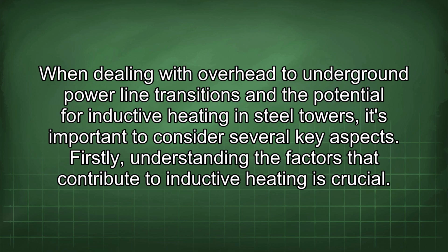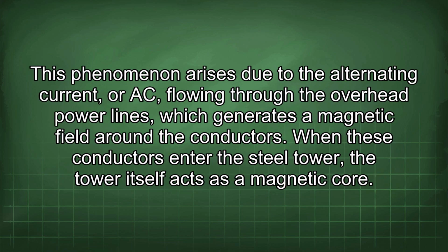Firstly, understanding the factors that contribute to inductive heating is crucial. This phenomenon arises due to the alternating current, or AC, flowing through the overhead power lines, which generates a magnetic field around the conductors. When these conductors enter the steel tower, the tower itself acts as a magnetic core.